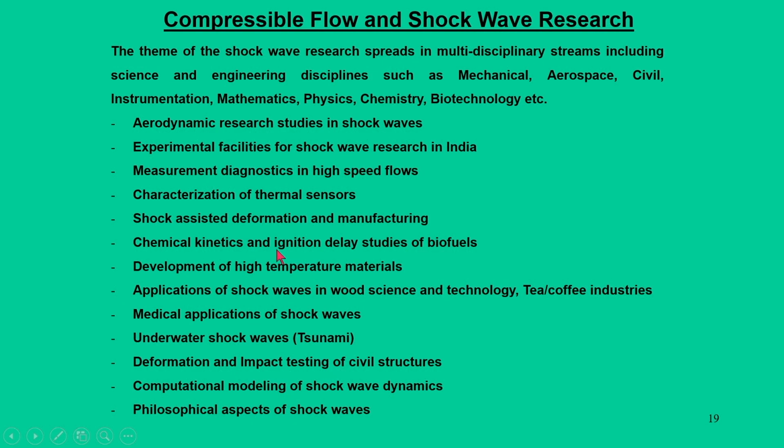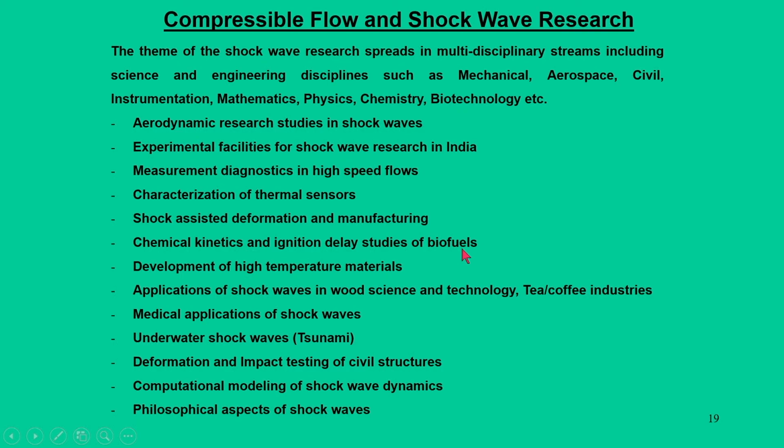Now, moving towards the engine side, we can think about potential biofuels, which are alternative fuels or next generation fuels. Since the shock tube can create an instantaneous high temperature, we can study the ignition delay of biofuels, because if such fuels are exposed to an instantaneous rise in temperature, how are they going to behave under those conditions. And it also leads to high temperature materials.